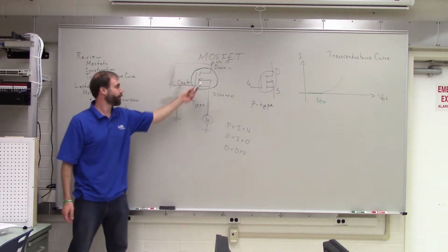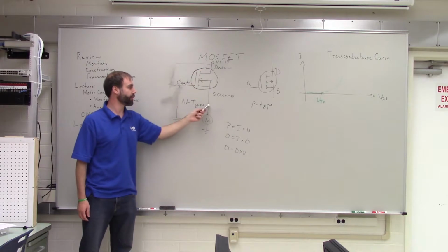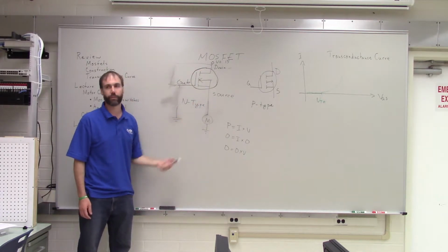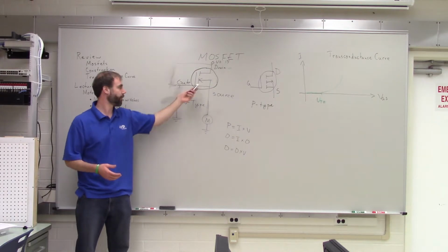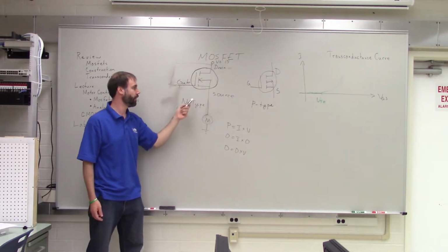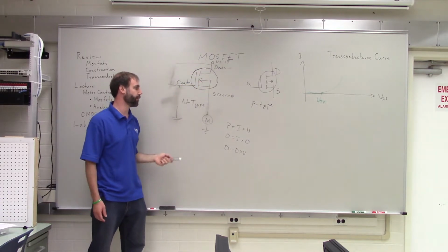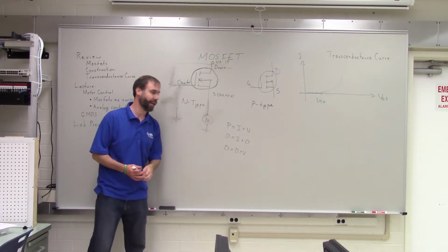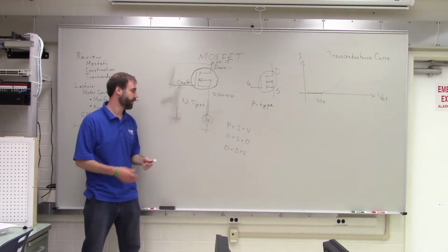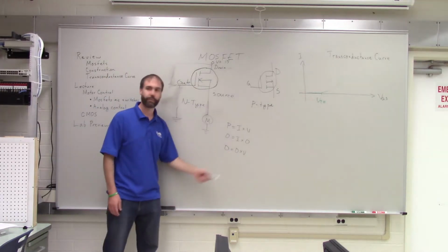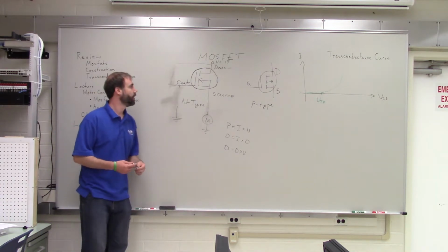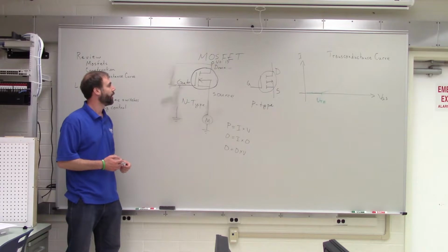So if there's no connection between the 15 volts and the motor, that would mean that there is no current flowing through there. It's basically a very, very, very high resistance. So no current, or almost no current, is allowed to flow. It's somewhere in the microamps, I think, is how much current is actually flowing. So it's essentially zero. Is that what you were asking? Okay.